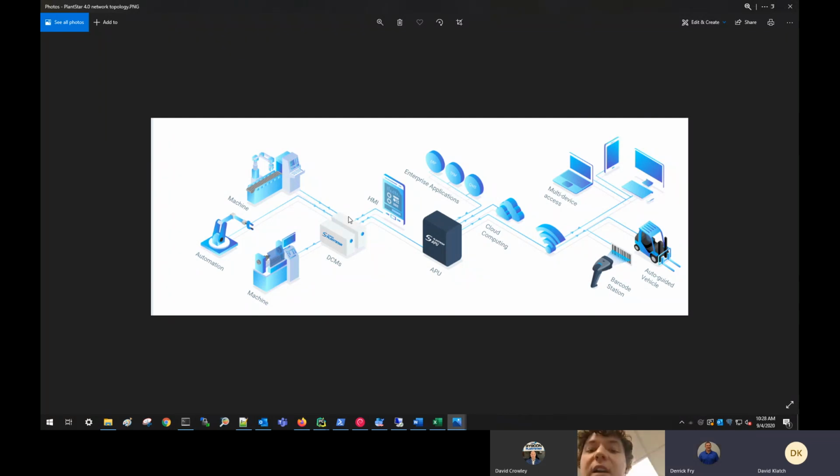But a simple example that actually does happen is if the machine goes down. That means there's a problem. The cycle didn't happen in the amount of time it was expected to happen. I'll talk more about what that means and how to configure it. The machine tells the DCM when the cycle started, and it's also supposed to tell it when the cycle ends. So if the DCM doesn't see that the cycle ended in the right amount of time, the machine is down, so it can send an output.